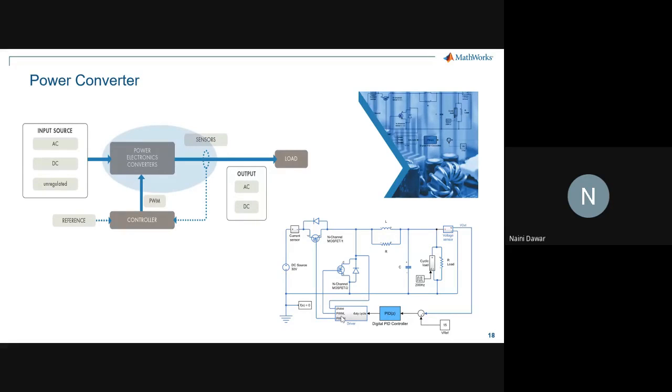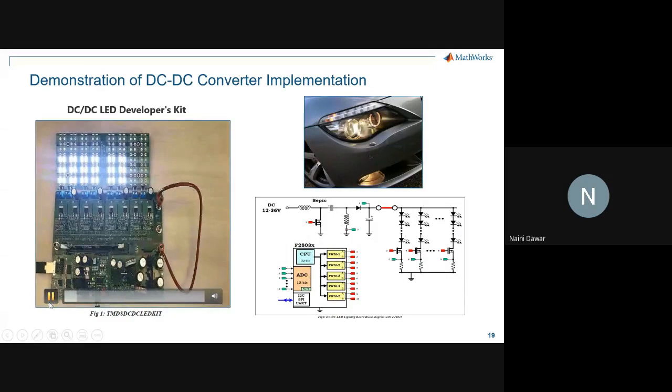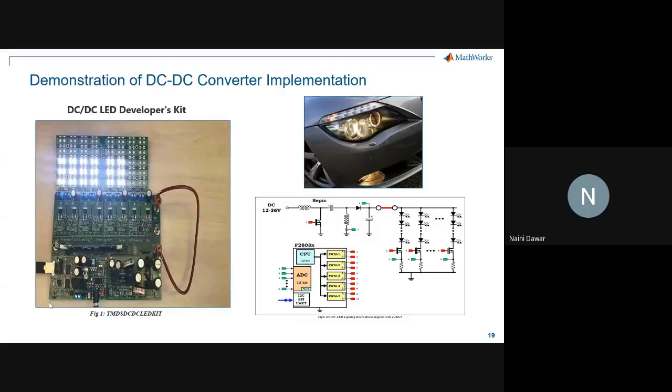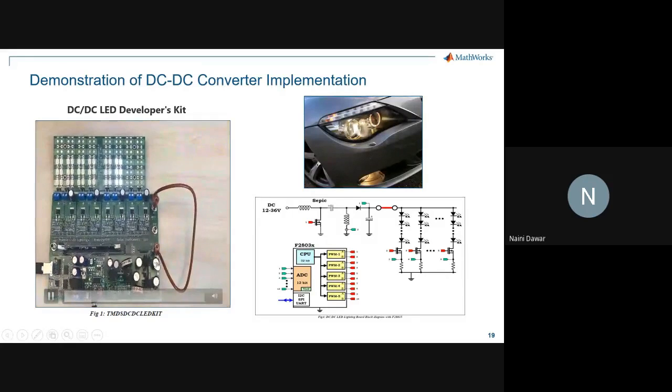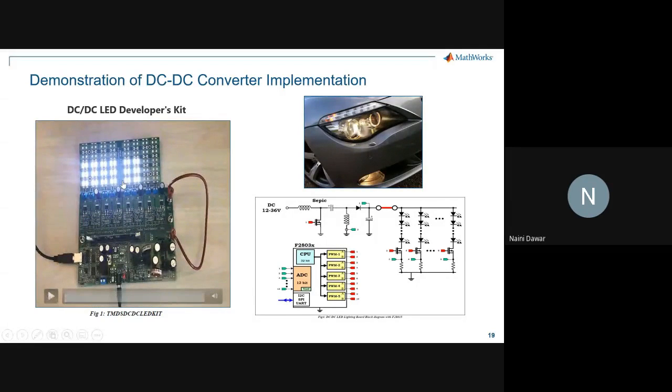These are for the converters. If somebody is working on nonlinear power converters, this is for the case of a DC to DC power converter. You also may need to design the controller for these. What we are showing here as a result demonstration is the end result. We have used the Texas Instruments DC-DC LED developer kit. This has a SEPIC converter in it, and we are trying to control the switching behavior of these LEDs. We are trying to switch on and off a specific LED, or manually control the brightness of these LEDs. This model we built with Simulink and Simscape.